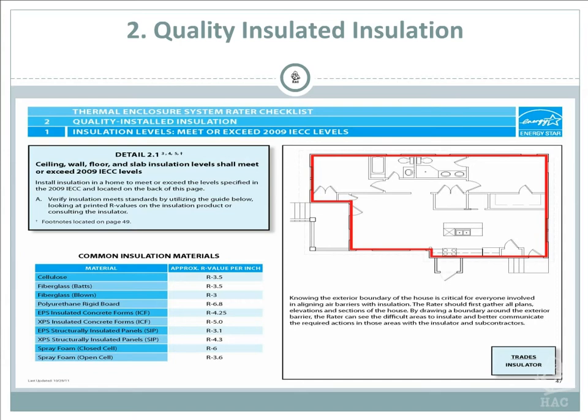You have to be greater than or equal to 133% of the required insulation. So again, you need to figure that calculation out. I figured it out at one time. It's like adding an R8 to whatever the minimum requirement is for that area. So in our area, it's an R30 in the attics. If you want to go Energy Star, then you have to go to an R38 minimum.